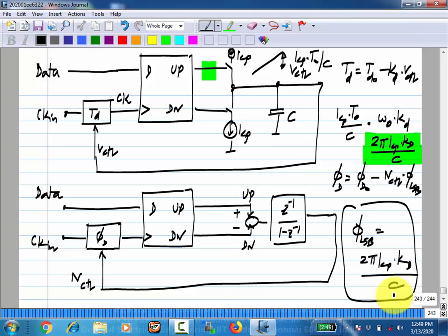It should be basically 1 cycle by 100 in this implementation. That corresponds to about a 7-bit type resolution, right? Typically, when you make digital implementations, you make everything in powers of 2. Why is that? What should happen to this accumulator? If you go on getting up signals, it will keep on accumulating. What should actually happen?